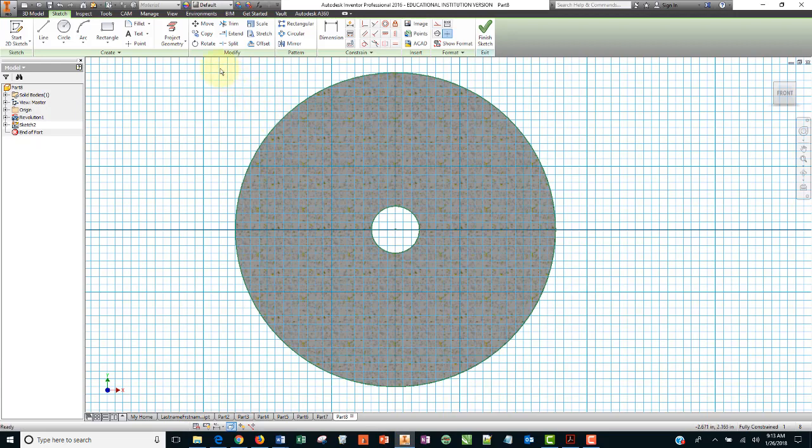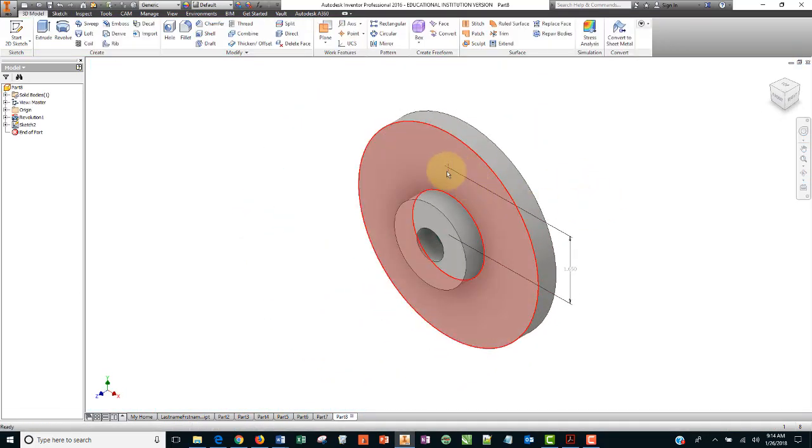So I am going to create a hole in the following way. Rather than make a circle and extrude it, I'm going to use the point tool, and I'm going to put it right on the axis here, as I'm told to, and then put that point a distance 1.650 above the origin.